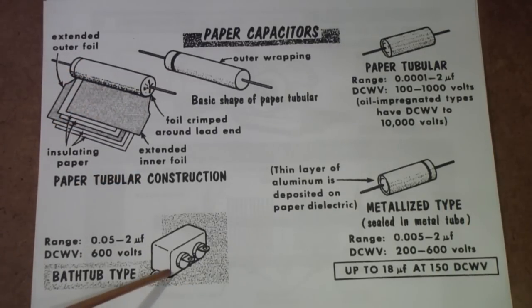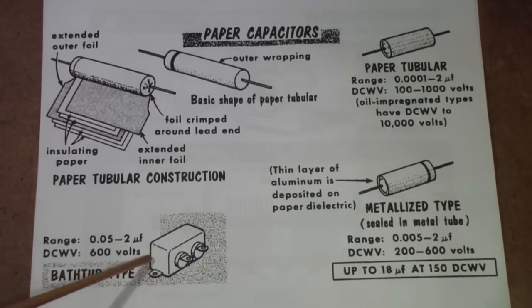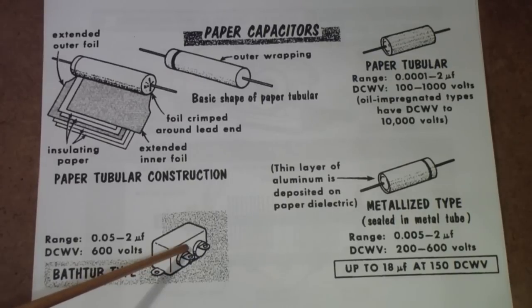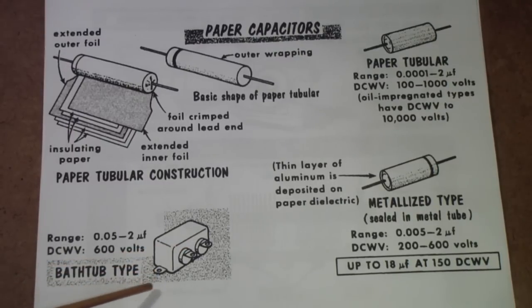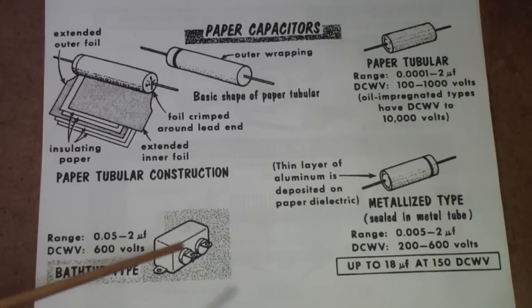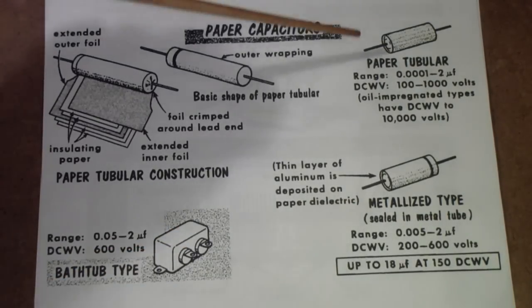They also make bathtub capacitors, and by bathtub they don't mean wet. They just mean they're in a plastic case, or sometimes it's phenolic. You see these a lot in old Philco radios, and the filler is often a fairly high temperature wax, and to open them up and to replace the capacitors inside, you have to melt the wax out. If you look at some of my restoration videos, you'll see this. There's also hundreds of others of people on the internet that have done the same thing.